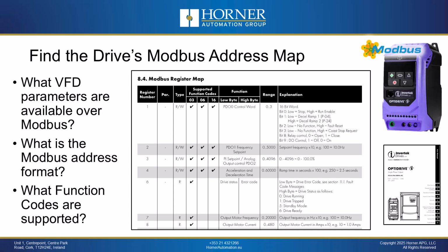In general, most drive manufacturers will have some form of control word, which will give you the ability to start and stop the drive and to clear faults. Some drive manufacturers may have individual bits to access Modbus for doing this. In the case of the Invertech drive we will be using, they use a control word approach for starting and stopping and clearing faults.